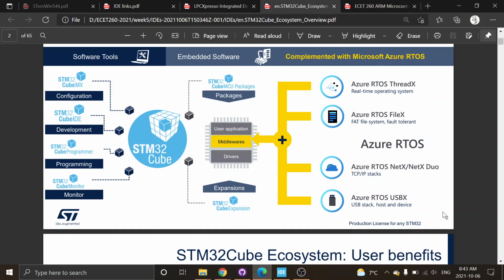One other thing somebody mentioned yesterday, the STM32Cube Monitor. There are a number of different monitors, and they unfortunately name them kind of the same. We're looking for just a straight monitor. They also have a power monitor. They have a motor control monitor, with some motor control application boards, and it will allow you to run a motor and look at the different features and affect what you're doing as far as tuning with PID algorithms.